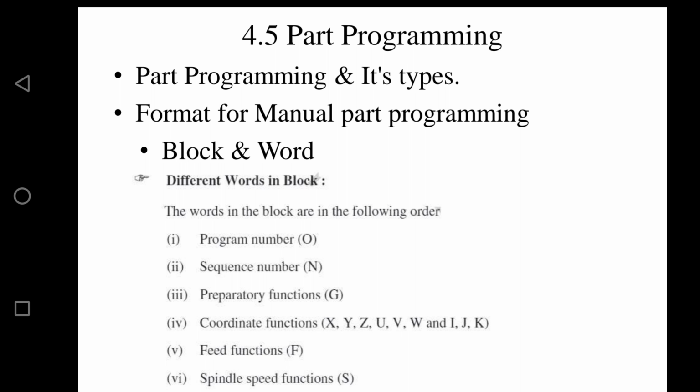A block is a group of words. Now you may ask me, what is a word? In a simple sense, a word is a coded instruction, and a block is a group of coded instructions. Each coded instruction in a part program is called a word.